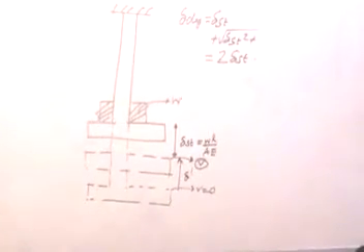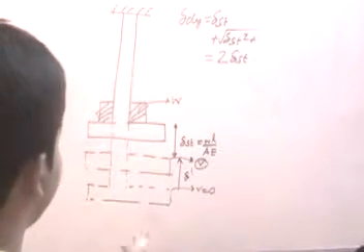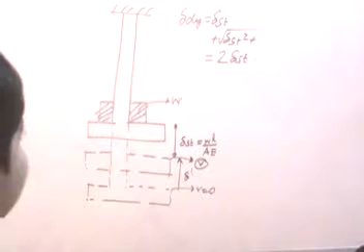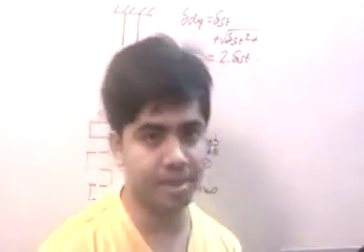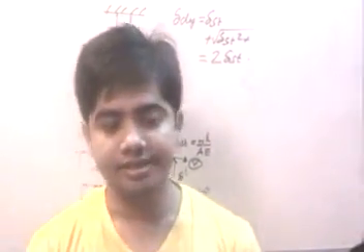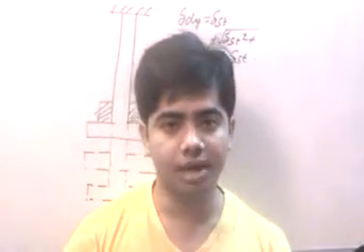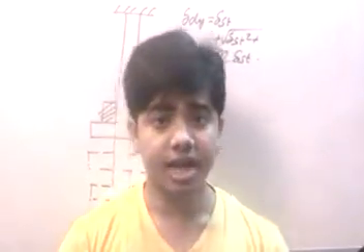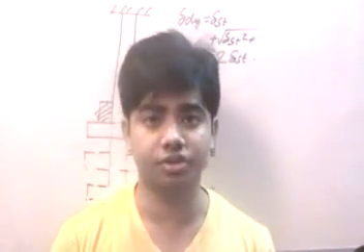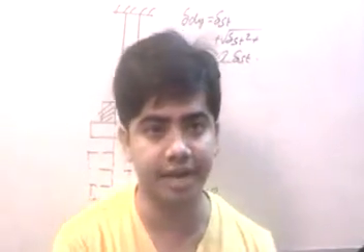So if we apply a certain kind of a suddenly applied load, right, then what will happen is that the deflection will be 2 times that of static loading, right? So this is essentially some sort of an amalgamation of dynamic and static loading in this case. And essentially, the brief synopsis is like this, that in case of static loading, for every increment of load, there is a corresponding increment in deflection, and there is no suddenly applied load as such, right? So what happens basically is that at every stage equilibrium is necessarily maintained, right?